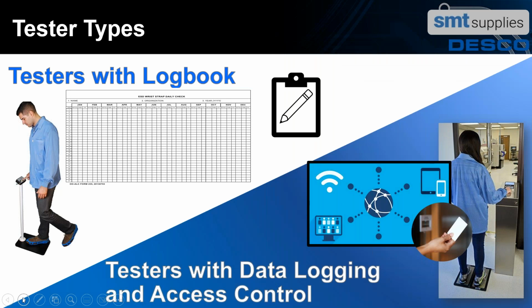Tester types. Okay, this is typical. Testers with a logbook, okay? This is the old standard where we have touch testing, like the person standing on the plate on the right side of the screen there. They plug their wrist strap in, or they're wearing their foot grounders. They press that button and they get a pass or fail, red light, green light. Some testers actually give you whether it's a fail high or a fail low notice, for instance, but you need to keep a written test log of that.